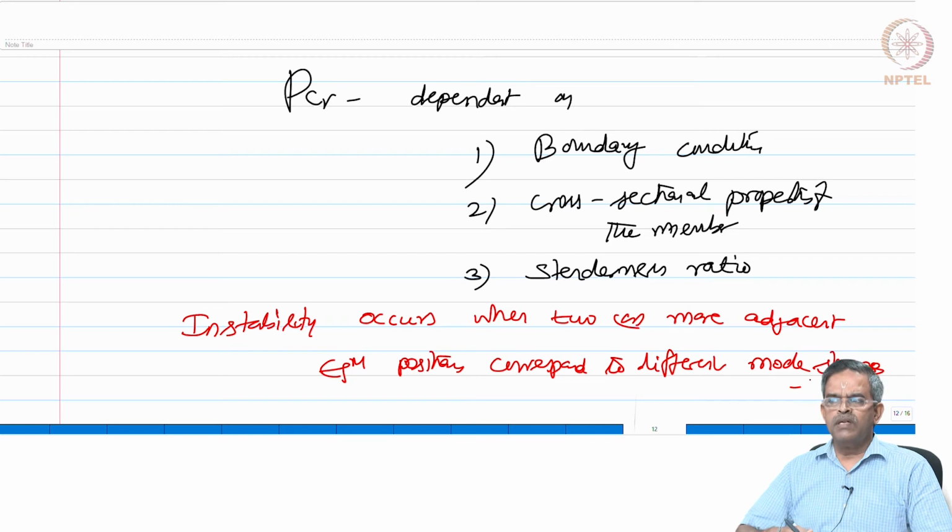So, when you talk about stability of offshore structures, it is more interesting, because we have form dominant design well practiced in offshore structures, therefore, we have to learn about this in detail, we should at least know about them. The advanced steel design is not meant only for offshore structural applications. Form dominance has existed for many years, for example, arches, domes, cable stay bridges. These are all statically indeterminate systems, they are all form dominant. Okay?